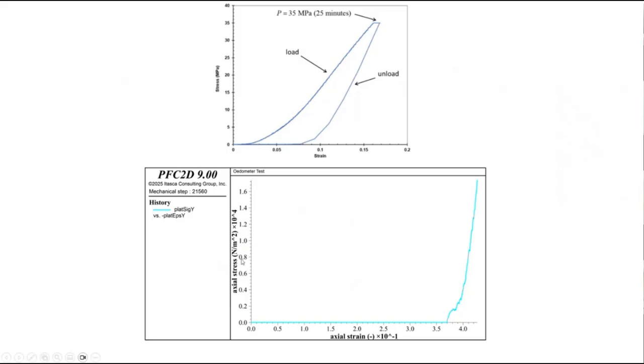So we got stress in pascals. And is this AOT? Is this your curve? Yes. And so AOT has stress in megapascals. So how much strain? The thing gets stiffened up after about 7% strain. And our strain, 7%, so that's 7,000. Okay, so let's just use this point right here for now. At this point, because ours is already stiffened up, let's look at this slope here to begin with. Do we have the same slope?